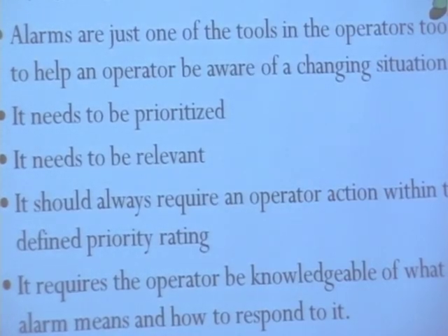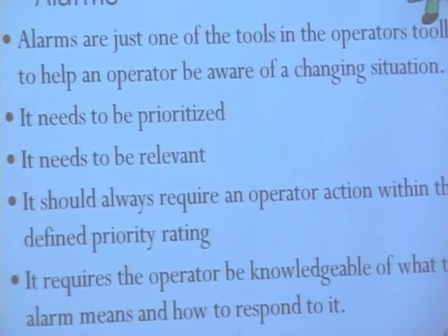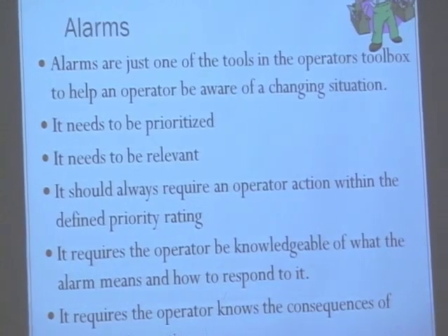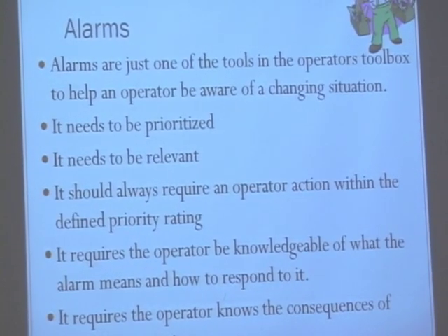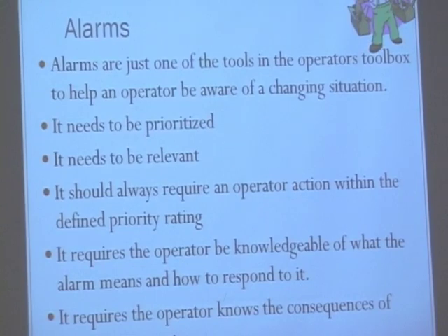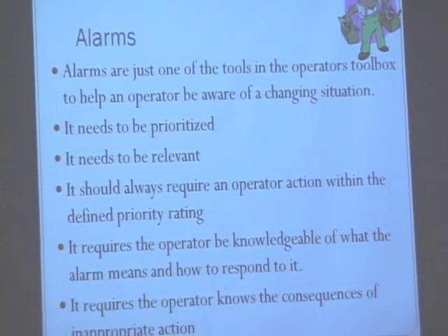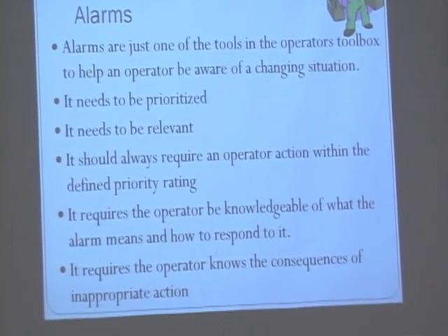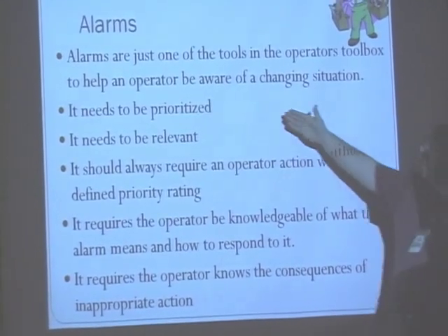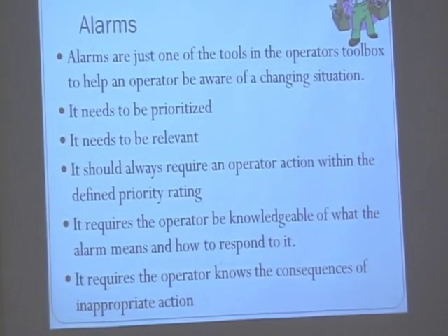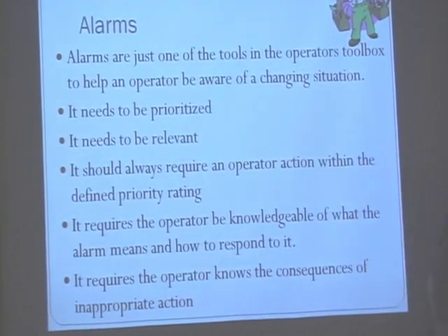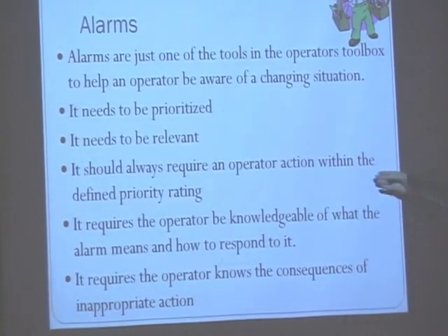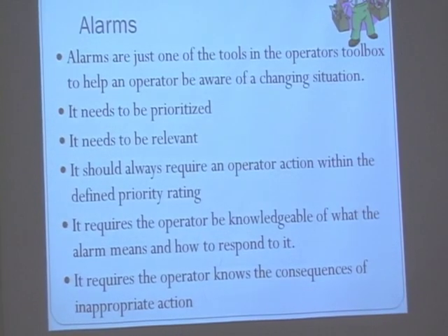Alarms, obviously, is a big one for us. But what we want to say about alarms is that alarms are just one of the tools in our toolbox to address situation awareness. Unfortunately, we've over-biased that, right? And we have far too many alarms today. Part of the issue is a lot of those alarms need to be prioritized and they're not. They need to be relevant and they're not. They should always require an operator action, but we see many that do not.